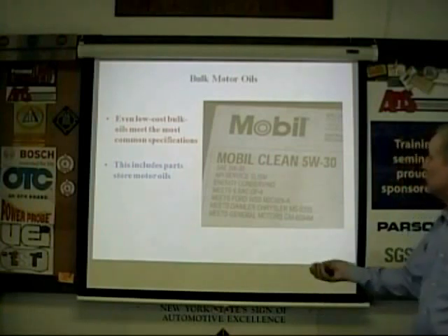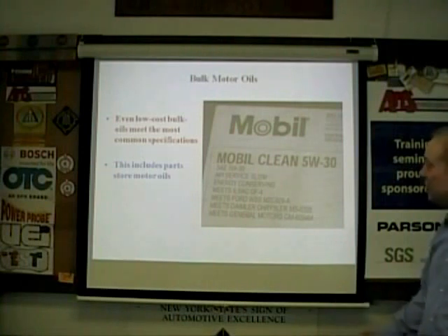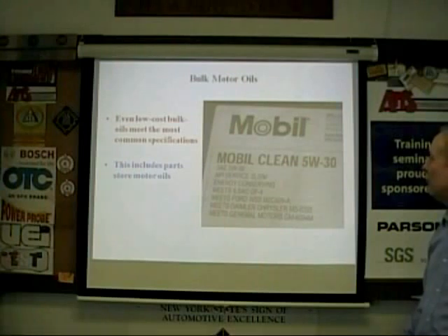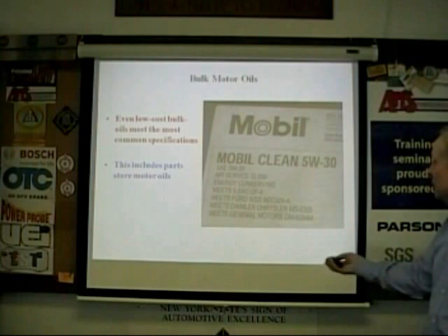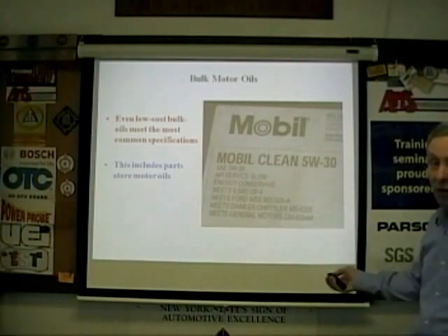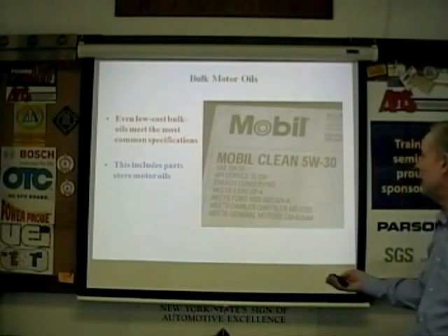This one here, if you look at this tag here, it says 5W30 SAE, API up to SM, energy conserving, ILSAC GF4, Ford, there's a Ford spec there, WSS-M2C929-A, Daimler Chrysler in this case, and GM, this 6094 spec. So it meets all of those. But again, you don't see a VW or you don't see a Mercedes. You don't see those specs on here. BMW, you don't see any of that on there.